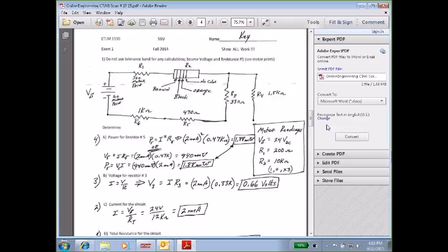As current flows through it, because the resistance of it is very high, it gets hot and begins to glow. It doesn't melt because it's in a vacuum, and it glows and gives off light. Now, when a light bulb burns out, that filament breaks or becomes an open circuit. No current can flow through it. So that's why a burned out light bulb is an example of an open circuit.